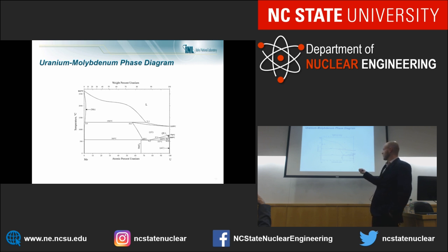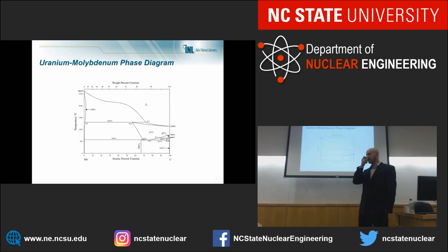However, we also have this intermetallic phase that's much closer in this system, but we are still dealing with primarily the BCC phase. One thing that's nice about U-Mo fuels is that it's been known since they were starting to be used that no matter what the initial microstructure is, it reverts to the BCC phase once it's in reactor. We don't fully understand this, but there's some kind of radiation stabilized phase transformation occurring in these systems, such that we have effectively pure BCC U or pure BCC U-Mo phases whenever we're in reactor, we think.